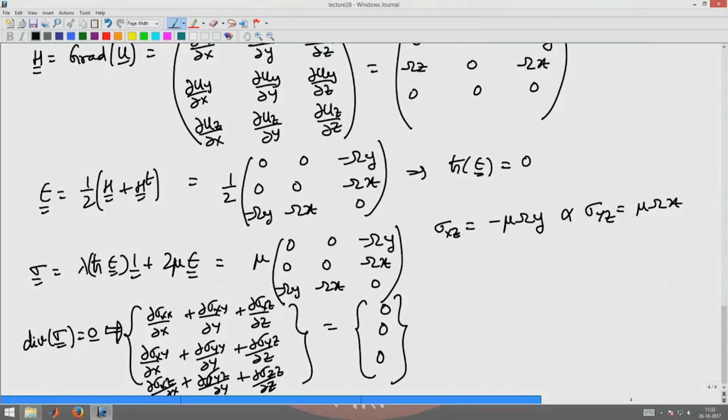Okay. Now the unknown is your angle of twist per unit length omega, which you will find from the requirement that the torque is given by the integral of sigma yz into x minus sigma xz into y dA over the cross section.